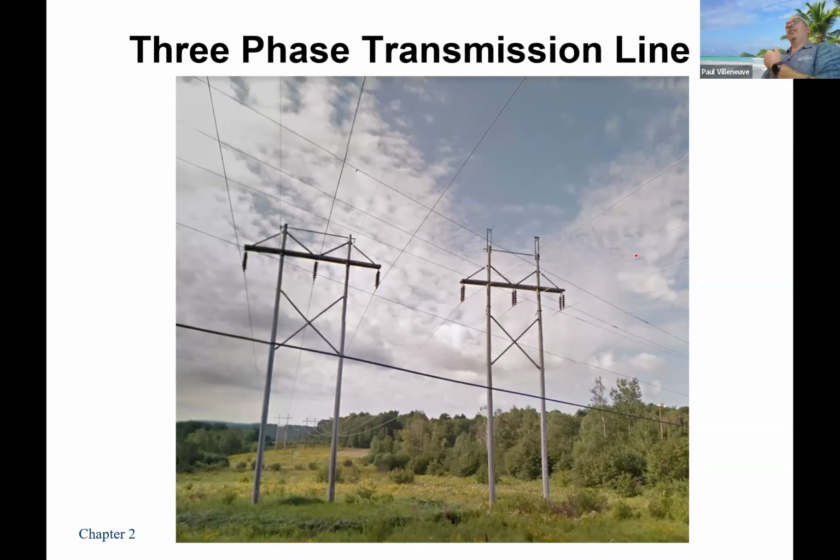pulling in either direction. All the attachments are kind of parallel to it, not parallel, but they're tangential to each other. They're pulling in opposite directions. It's when something comes in this way and goes out this way, now I've got to have an opposing force in this direction and one in this direction. That's why you're going to have guy wires.